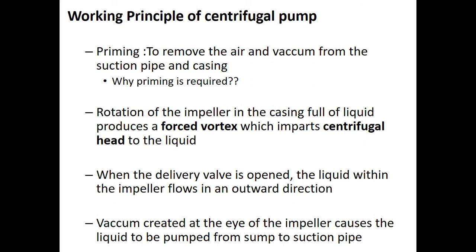Now, what will happen if the impeller is made to rotate in the presence of air? The vacuum created may not be sufficient to lift the water from the sump to the impeller. So that is why we do the priming. You may expect this as a 2 mark or 4 mark question: why is priming required? So it is very important to prime a centrifugal pump.